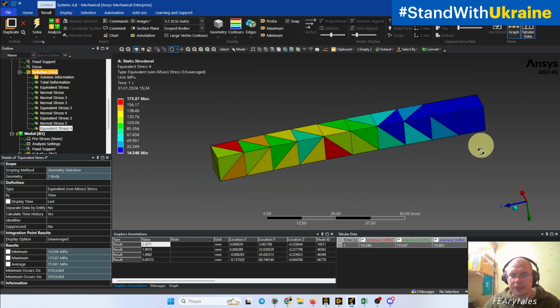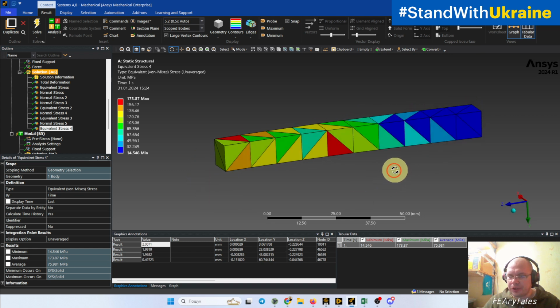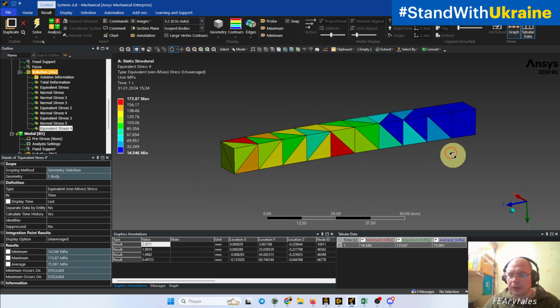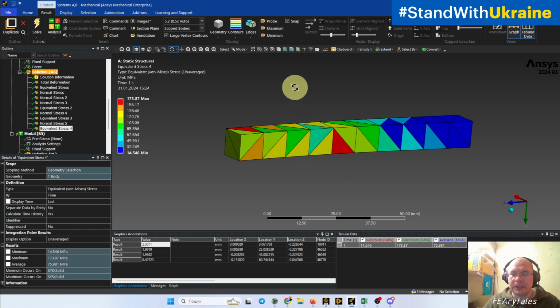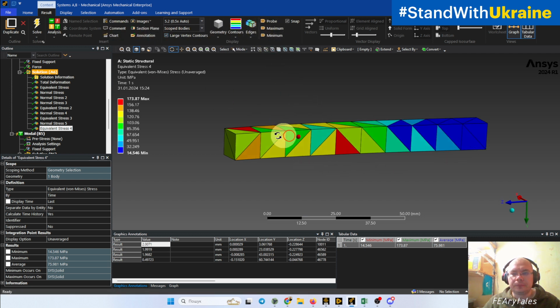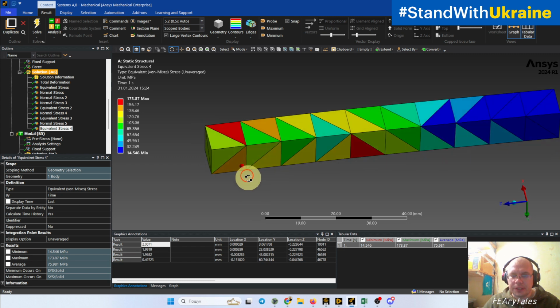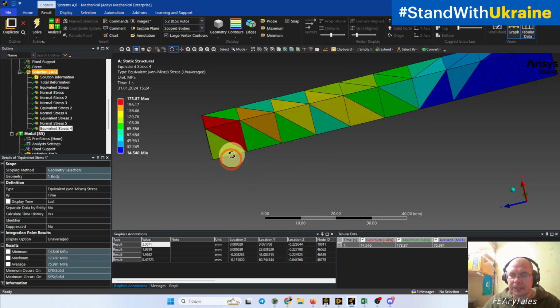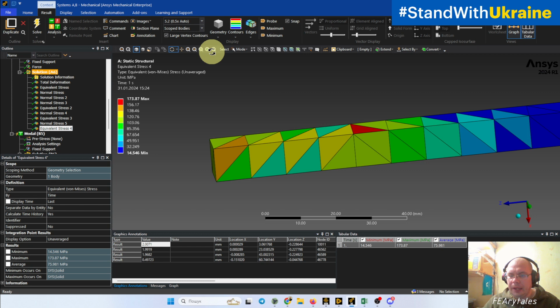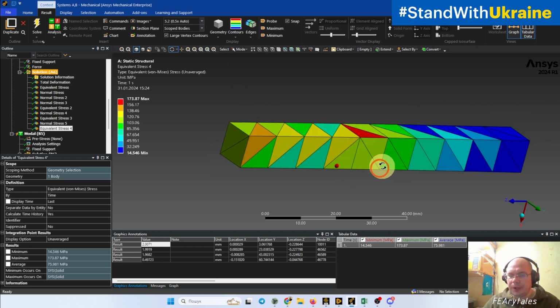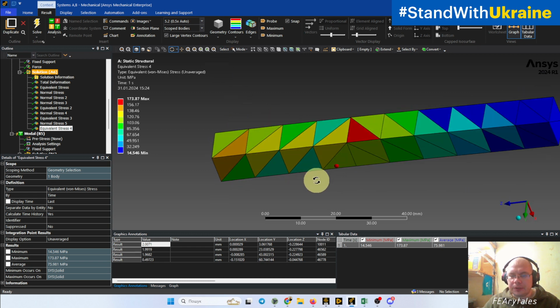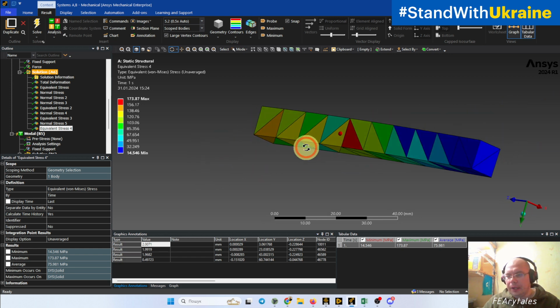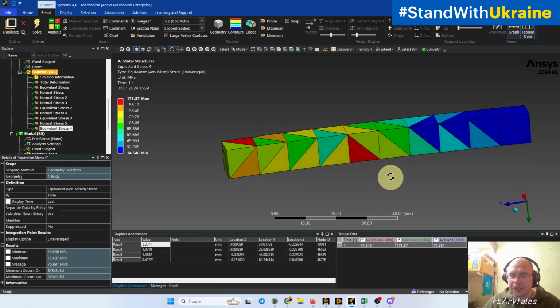And this is an averaged von Mises stress for our beam with linear tetra element. And we can see that there is no linear stress distribution between the nodes, we can see the constant color for any element. We need to understand that the mesh here looks very different and came in a very strange way.